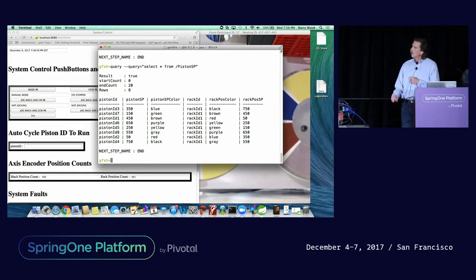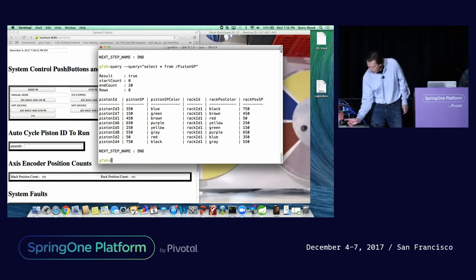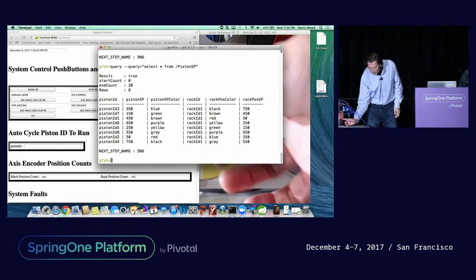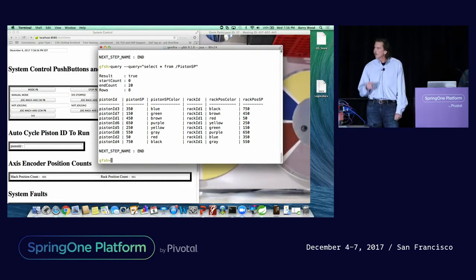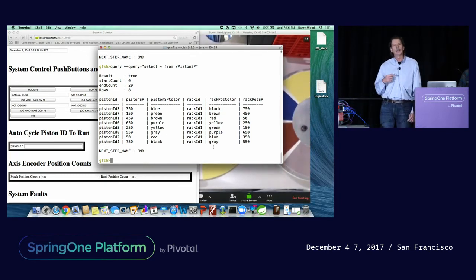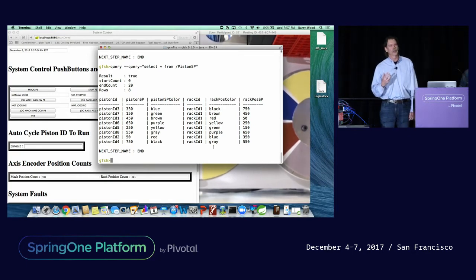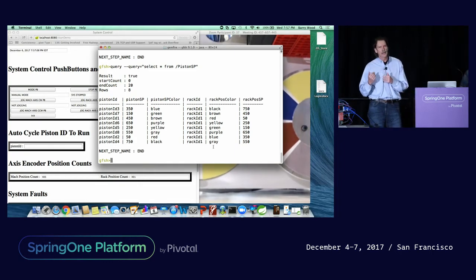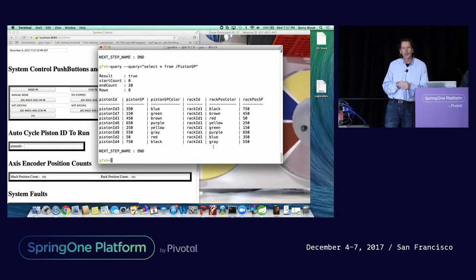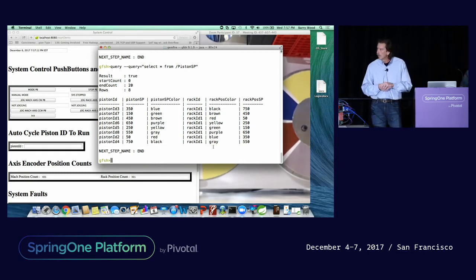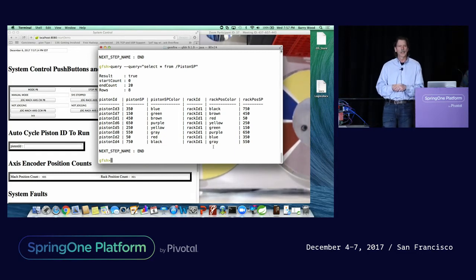Then we're going to move to that color segment, and then we're going to make 12 variances, to simulate the process variance. We're going to capture those variances, bring them out to the screen, and do some simple statistics on them by looking at the average, the min, and the max of those values.